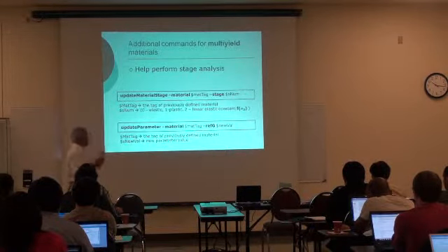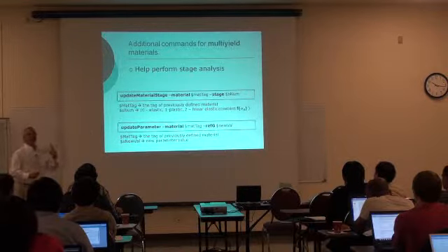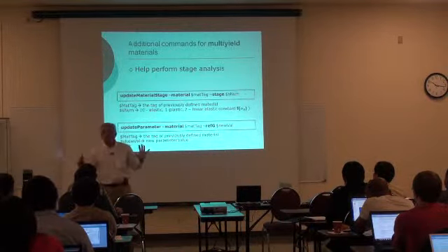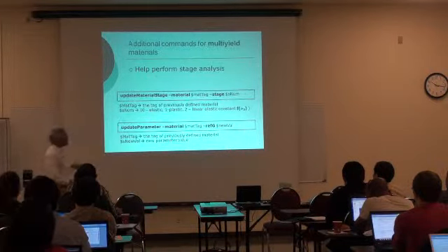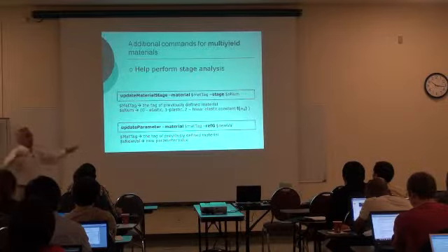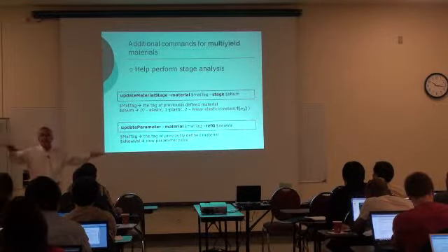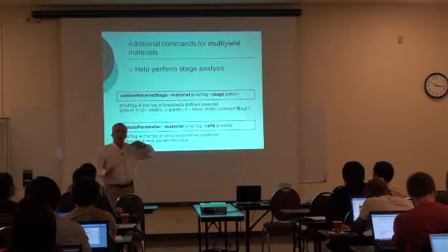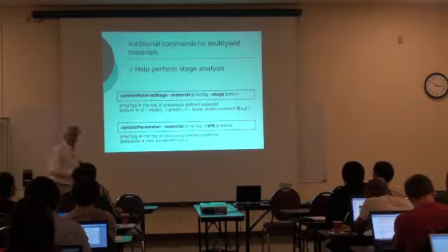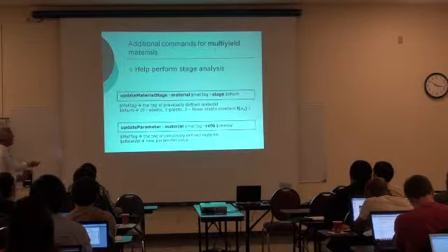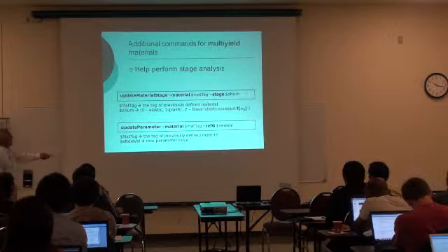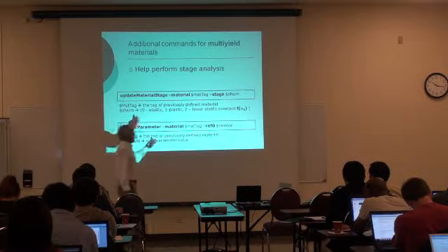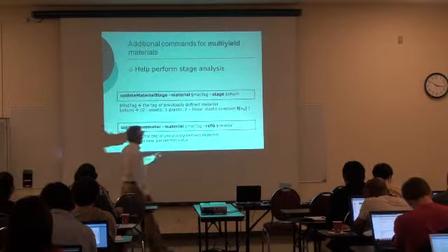If you do that and you are using an elastoplastic constitutive model, your mesh will fly, because that is not possible. So one way to overcome that is to assume that the initial state is elastic. Once we have the elastic state of stress, then we switch the material to plastic. When you do that, all the variables will start shaking. But after a couple of steps, the system gets into equilibrium and the results are appropriate. So with this command, update material stage, if the stage is 0, it is elastic. If it is 1, it is plastic. And if it is 2, it is linear elastic as a function of the effective stress.